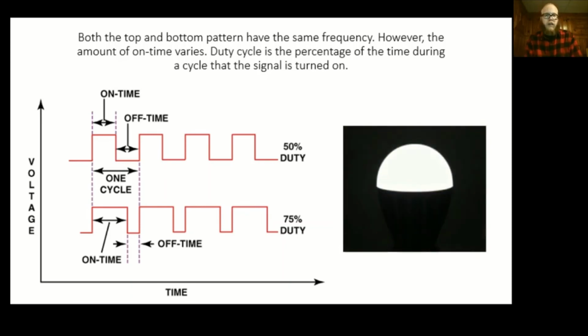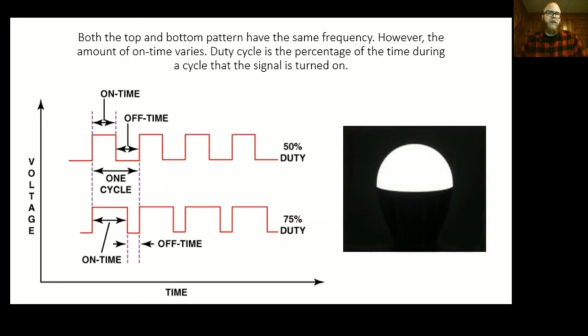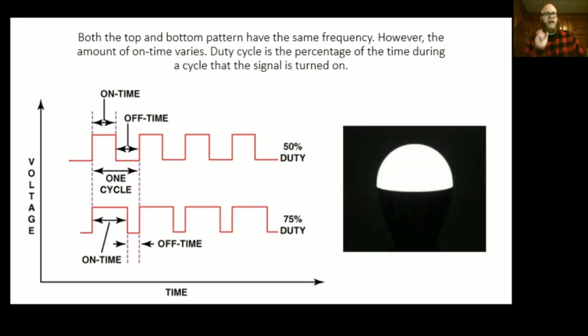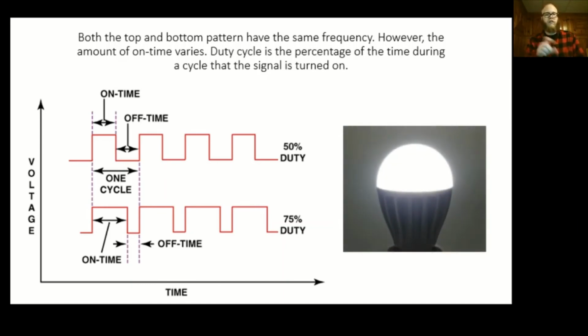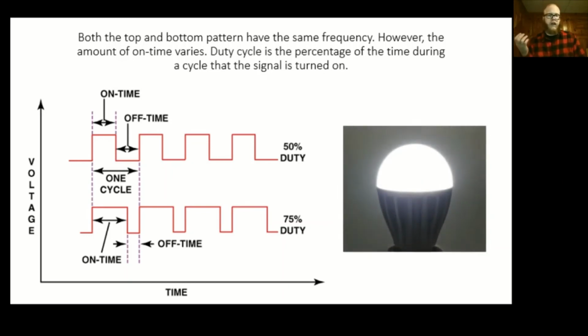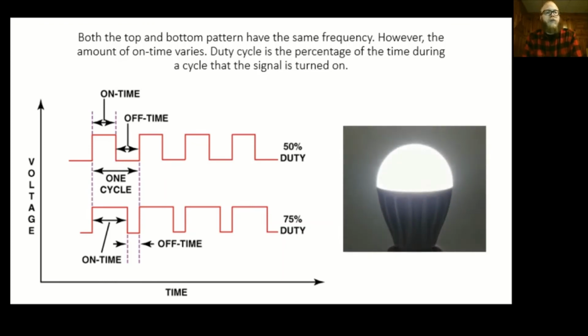And then the last topic I want to talk about is pulse width, which is often referred to when dealing with engine performance, where the pulse width of our fuel injector is 1 millisecond, so 0.001 seconds, while the vehicle's just sitting there idling. The pulse width is just, there's no consistent hertz rate, right? There's not a consistent rate, because the engine's going to change speeds all the time, so the cycles are going to change with the speed of the engine. So what they care about is how long is the fuel injector on for. That's pulse width. How much time was it on for?